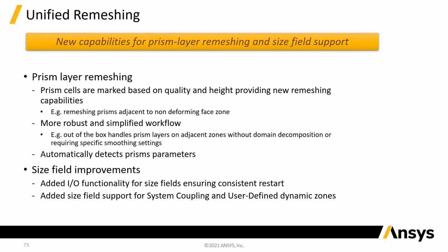So imagine you're doing a simulation of a ball flying through the air in a moving mesh. Then you would probably start off with quite a coarse background mesh and a nice refinement around the ball. If you don't do anything special and start remeshing, that refinement stays where it is in physical space, and the ball just goes out into coarse mesh, and when it's remeshed, it stays coarse.